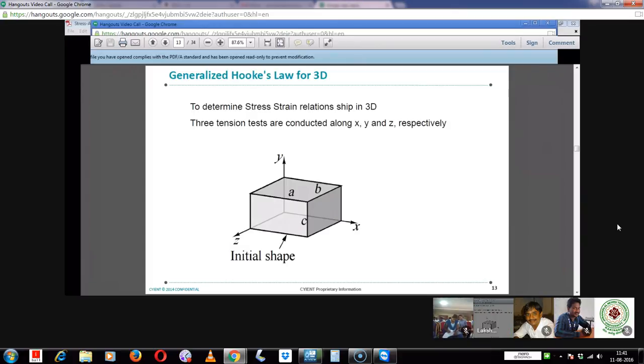subjected to gas loads. Gas loads will flow uniformly for all the centrifugal, cylindrical. Gas flow will be uniform, and there will be some thermal gradients. So all these blades are subjected to uniform loads: pressure, thermal, and angular velocities. So, is it good to analyze all the blades when it is subjected to uniform loading? May not be. So a single blade is sufficient to do the analysis. That is a simple analysis.